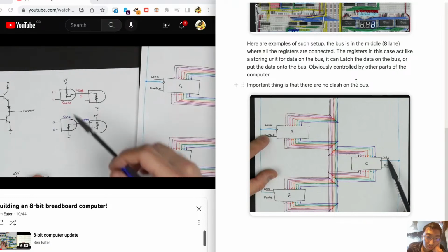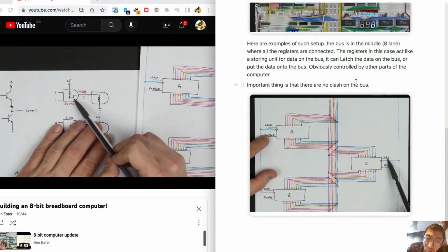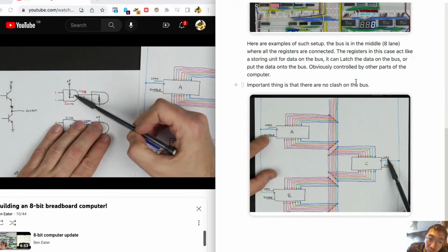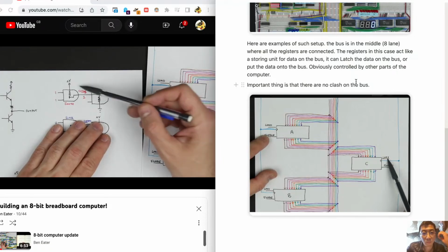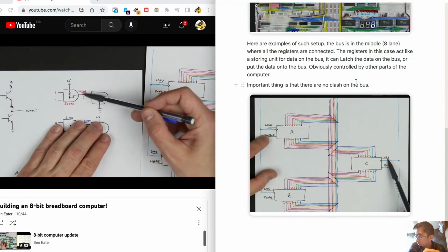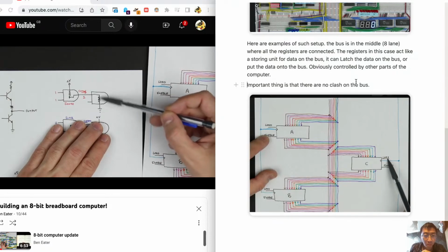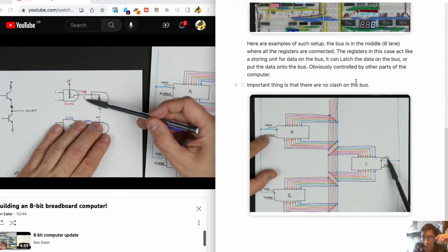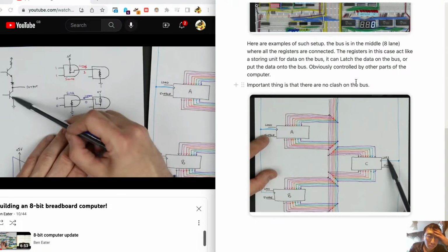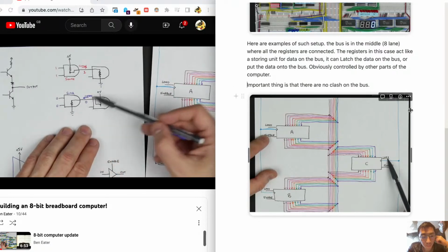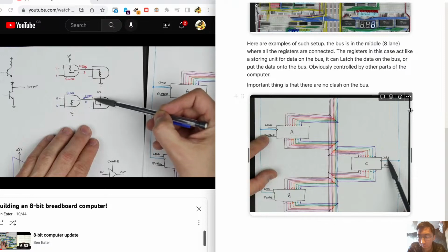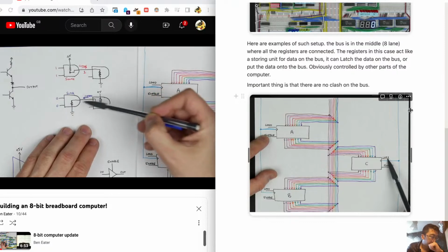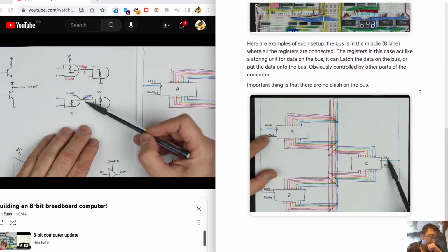So another way to look at that is like this, where when the gate is on, there's this resistor that essentially connects you to the output. So sort of a resistor goes to the output. And then on the input here, what that means is that current can flow out of this output and then to ground in the next gate. And so current flowing this direction is seen as a 1. Alternatively, if the bottom transistor is turned on, then we have this scenario here where current can be sunk essentially into that output to ground. And when current is flowing this way, we consider that a 0.